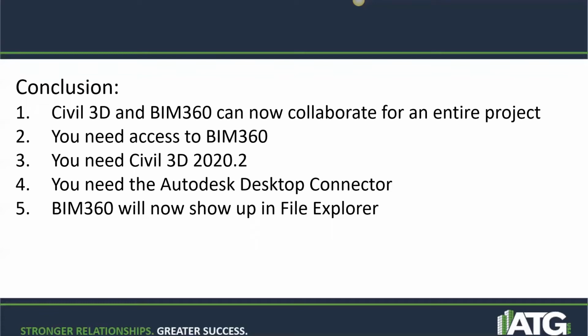And so again, the conclusion, you can now collaborate entire projects online. You just need an account to BIM360. You need Civil 3D 2020.2, the Autodesk Desktop Connector app. And when you have all three of those, BIM360 will then show up in your File Explorer.